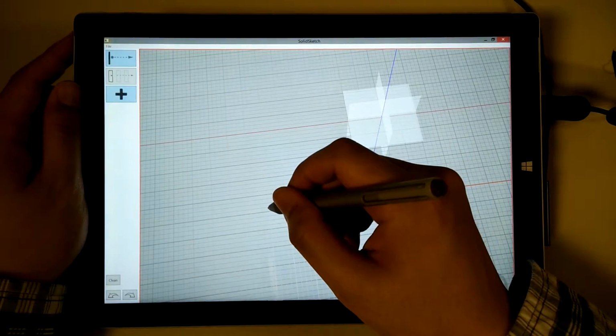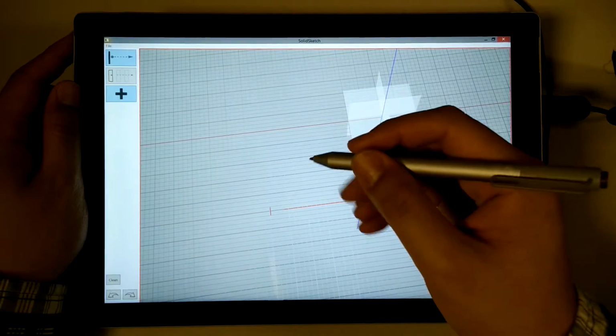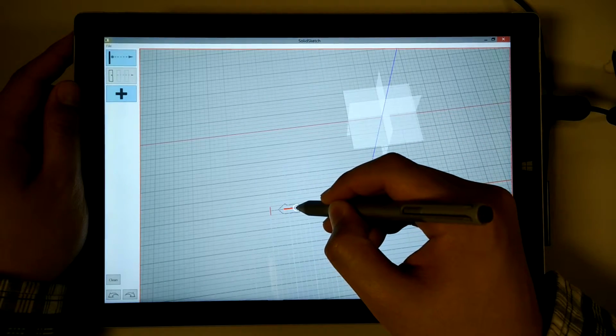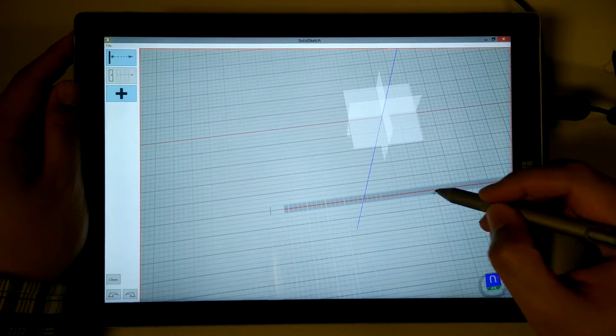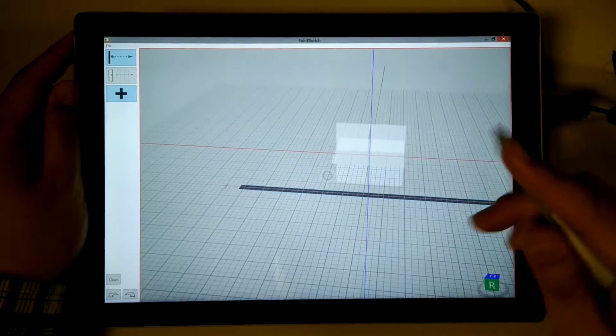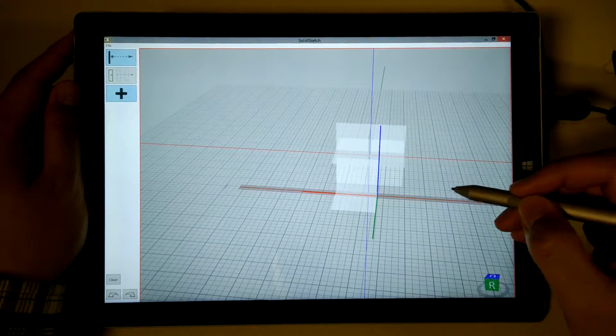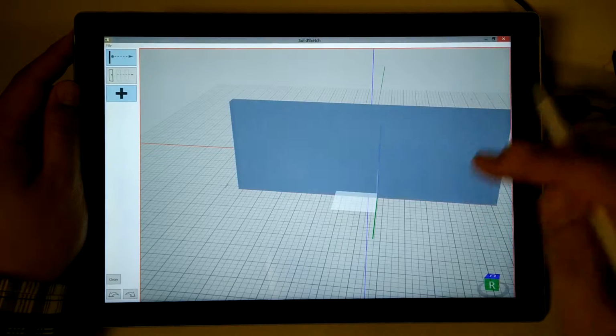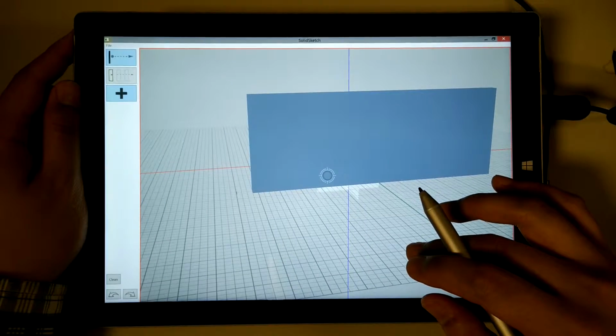For example, we first draw a short line segment to represent the width. When the Extend Dimension button is selected as shown in the upper left corner of the UI, the user can extend the selected line segment and trace the template line to generate a 2D offset surface, which becomes the profile shape of the wall. The same Extend Dimension rule will extrude the 2D surface to 3D geometry.